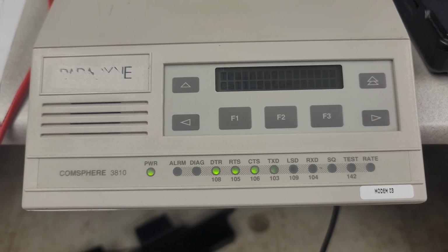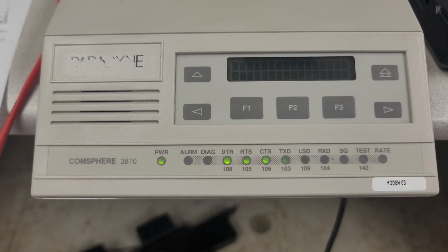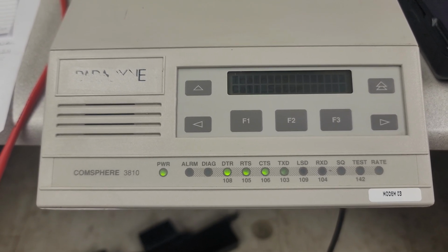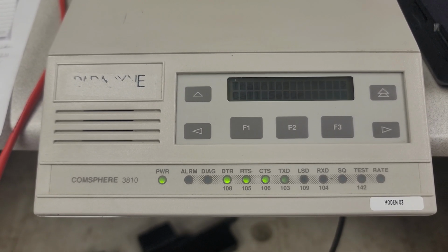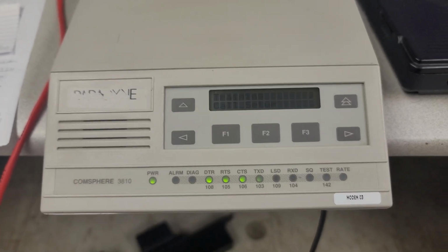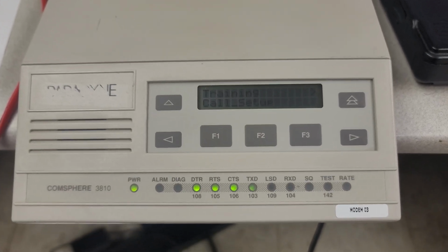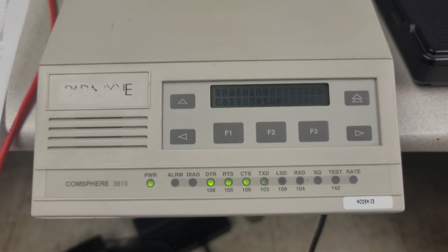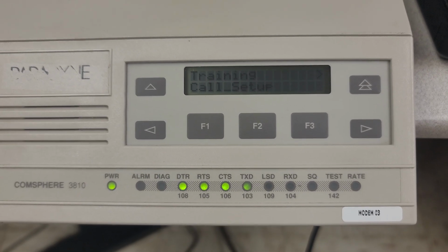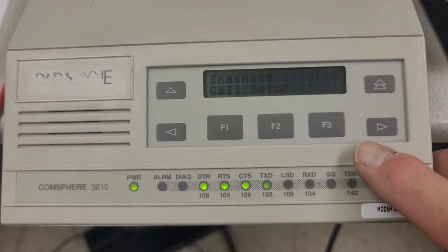So these Paradyne modems we're using to transport V.24 from a remote site with a base station or a receiver on them over a T1. The V.24 cable on the remote end is a straight through V.24. So there are some settings in these modems that we need to change in order to get them to sync up and operate. I'm going to take you through them real quick.